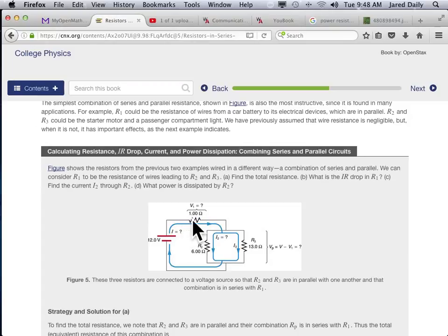So you gotta figure out the total before you figure out each second. Yep. So once we figured out the total current, we know that all of it has to go through this resistor. When it gets here, the current can split. But when it goes through this resistor, it only has one path to follow, so it has to go through there. Current cannot disappear. It has to be conserved.